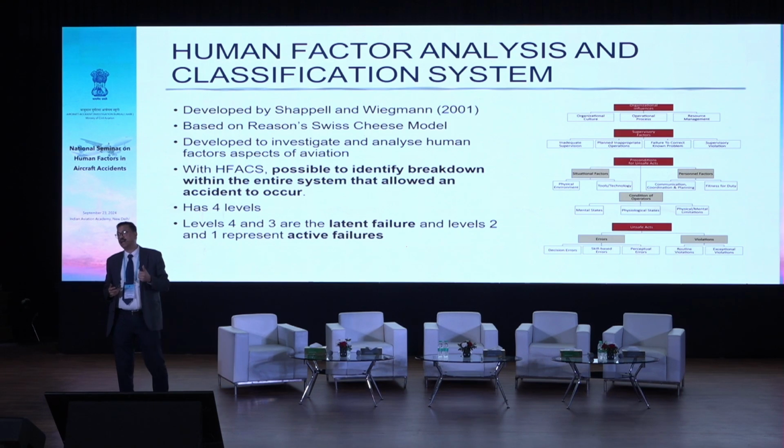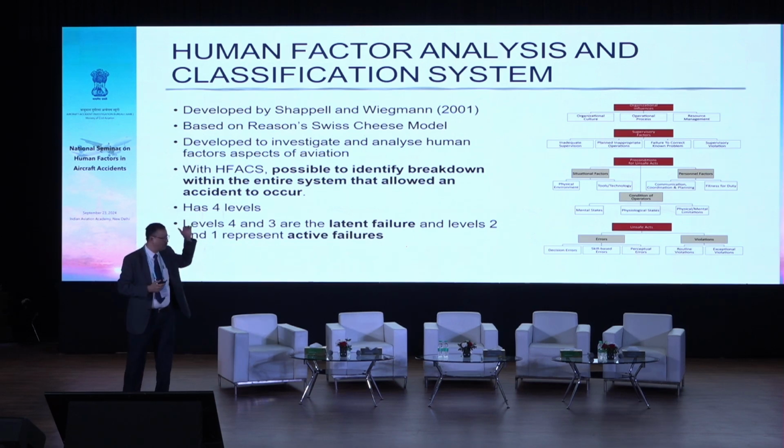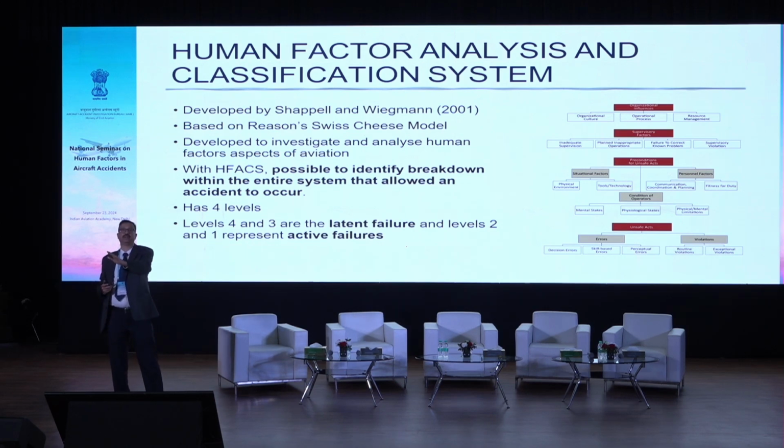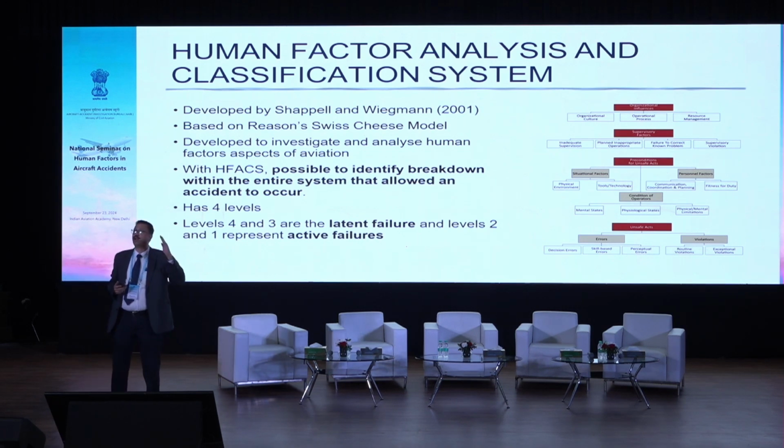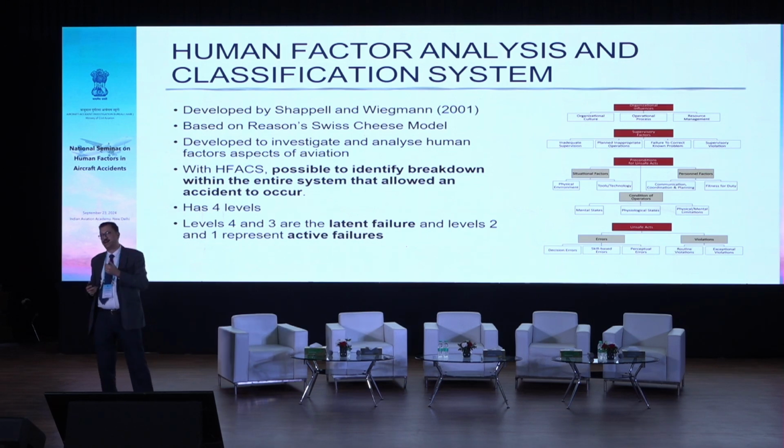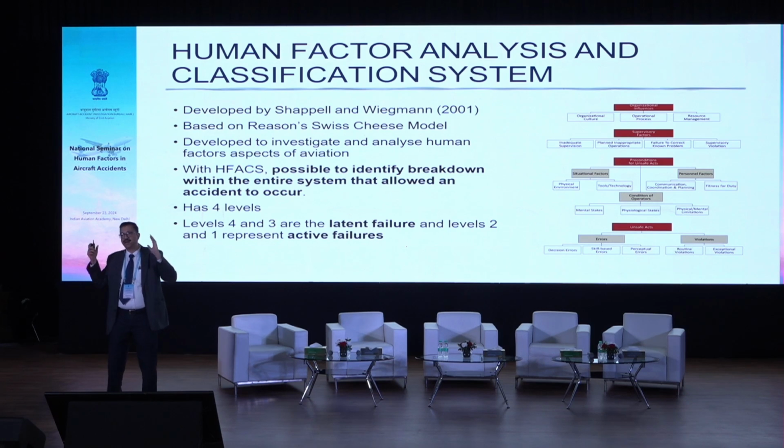So gentlemen, we have to be very clear about one thing. When we are investigating, there's no getting away. It is our duty as an investigator to look at all these elements and bring forward that these are the contributory factors. Annex 13 still talks about a probable cause. Some investigating authorities, namely like the Australian Transportation Safety Board, have moved away from the concept of probable cause. They have filed a difference with ICAO, and they have said that we will only now come up with contributory factors so that the system gets addressed.